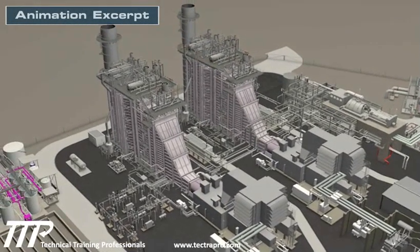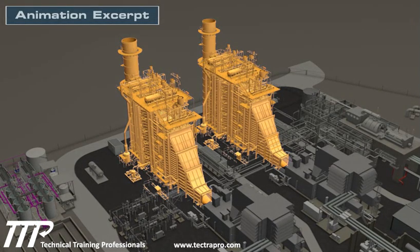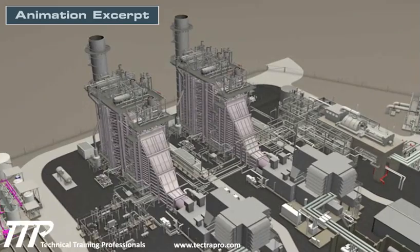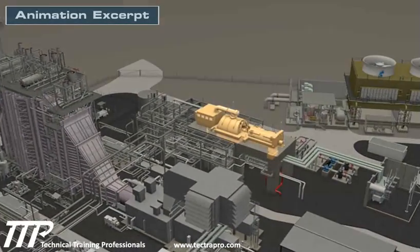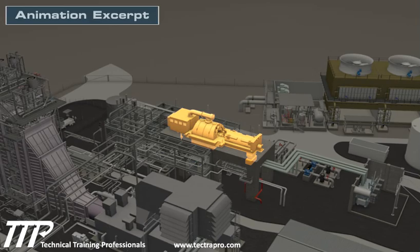The exhaust from the gas turbines will pass through the heat recovery steam generators to capture the energy of the exhaust gas. This energy is used to boil water at 3 pressures for use in the steam turbine, producing up to 40% more power from the plant from the same amount of natural gas.